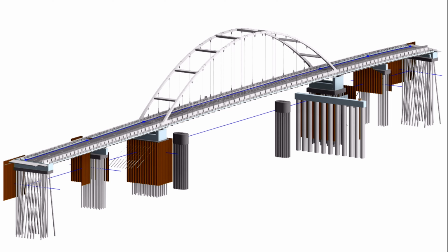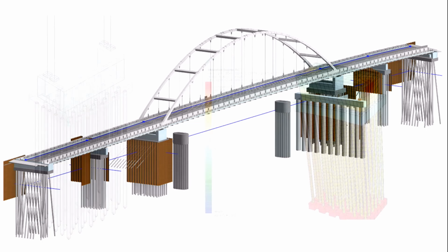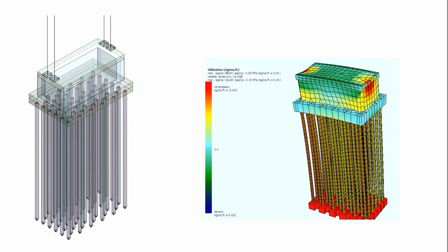Because those elements are all Revit type components, we could use the geometry to do the analysis in Sofistik. We did not do it for the whole steel bridge, unfortunately. It turned out to be a bit too complex, and we had a time limit, but we did export all the supports into Sofistik, and that worked really, really well.